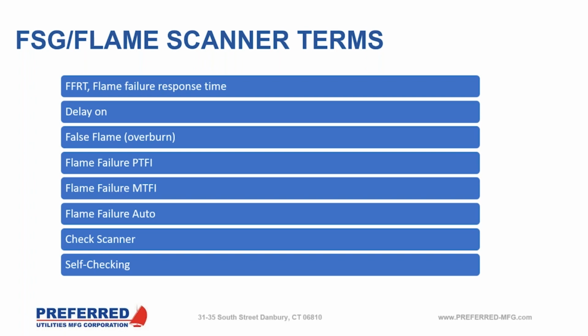Now, sometimes depending on the size of the burner, this flame failure response time could be as low as even 1 second, but it just depends on the particular application. So flame failure response time, very important.